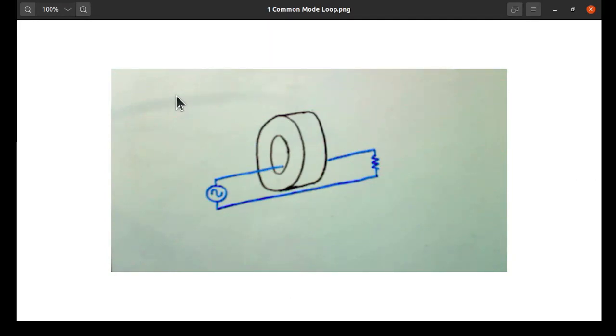You'll find them on cables that go to your computer. USB generally have a little barrel at the end of the connector, or behind the connector, and this is a ferrite application. And it's suited to this kind of situation where we have a loop going through the core of this bead. So this is a continuous wire to a load, to a continuous wire back to a source.